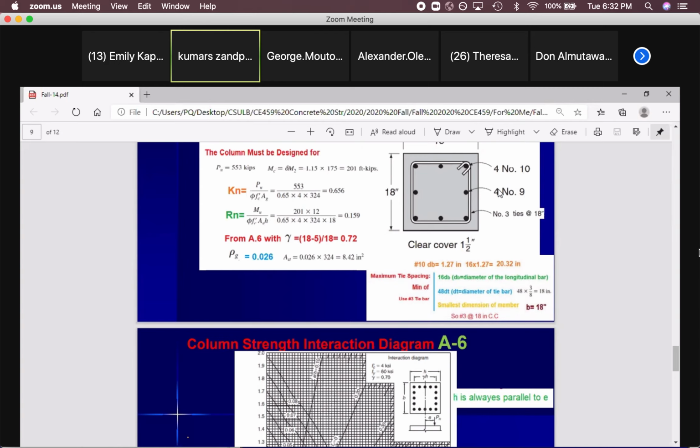Just remember, in an exam or any test in future or in real design, if you make a wrong calculation and instead of considering that as a slender column, you go with just a short column, you made some mistake and the numbers came out with actually not a slender column, then as you can see, instead of considering 2 or 1, you will go with 175. And you will use less rebar. You must pay attention to all those parts in the code. And those are not hard.